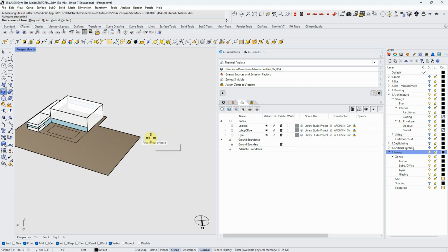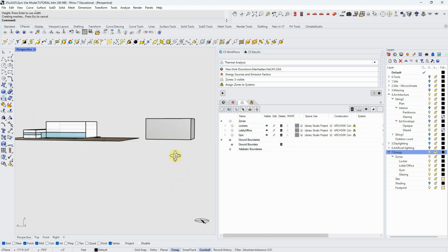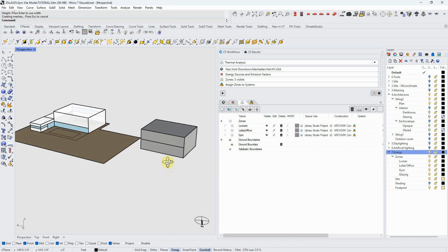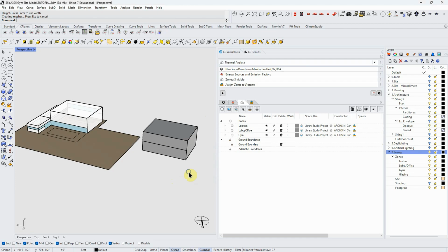The way to create a zone is with whatever you've got. Let's say you've got your daylighting design and separate surfaces, however you've laid it out, with your windows maybe as punched openings. To make thermal zones, what you want to do is just make an extrusion. The way to think about it is that a thermal zone is just a volume of air, so I'm separating out a volume of air with that extrusion. I'm going to add a surface to it so that I can have a window. So now I've got an extrusion and a surface that's coplanar with one of the surfaces in my extrusion.